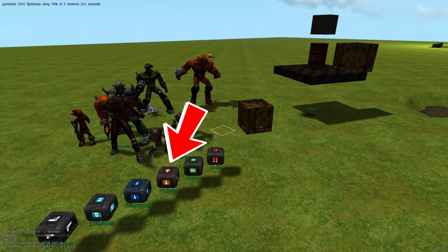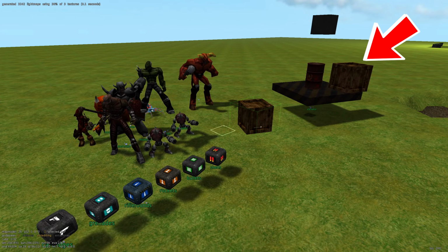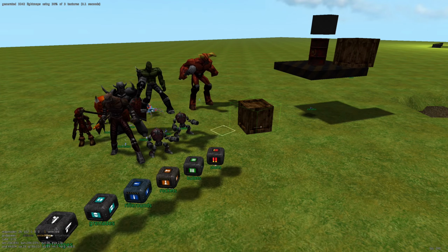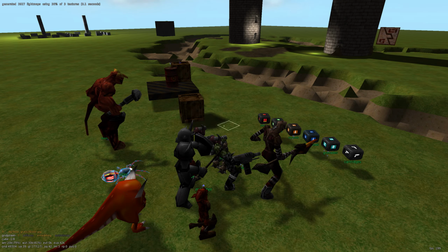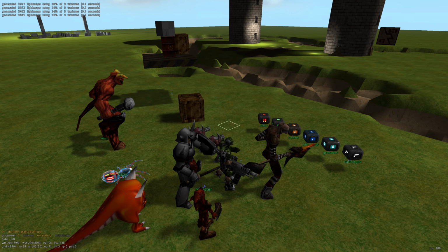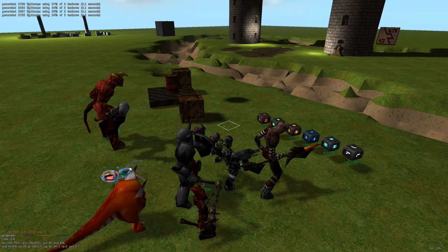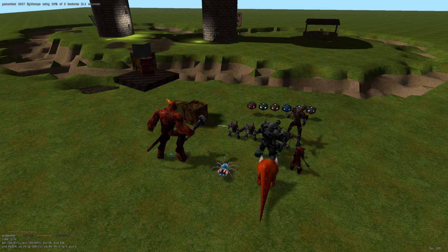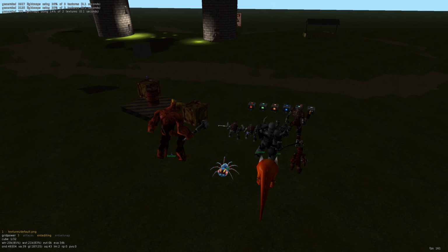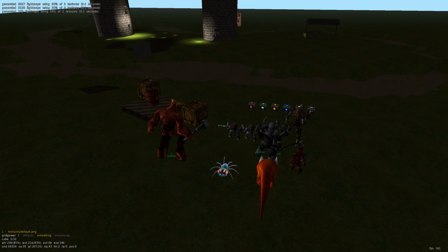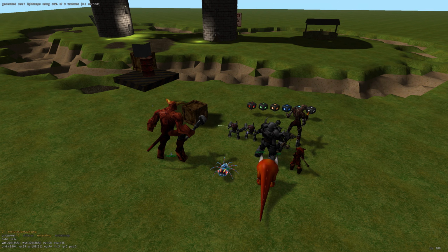Therefore, players, pickups, monsters, barrels, boxes and elevators, most of which we will learn more about in later episodes, will cast dynamic shadows. But another exception about sunlight is that only the sunlight yaw affects the direction of dynamic shadows. The pitch only controls their prominence. In other words, a pitch of 0 will make dynamic shadows disappear or fade out entirely, while higher values will make them slowly reappear.